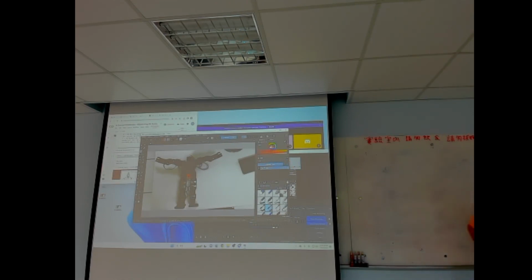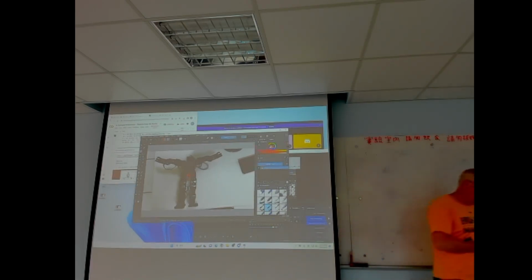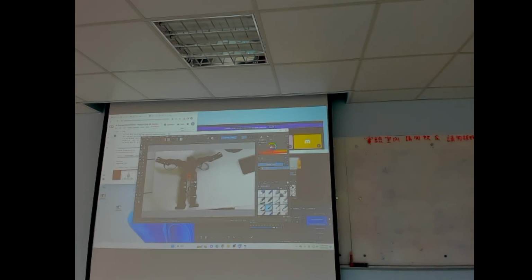Now, for the coordinate systems attached to the joint, we have a very strong convention that the axis of actuation corresponds to the z-axis. That's what we discussed last class. Which means that if I have a coordinate system, x, y, z, make it a right-handed coordinate system.